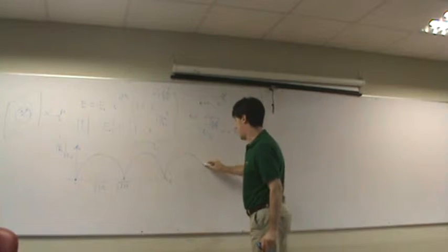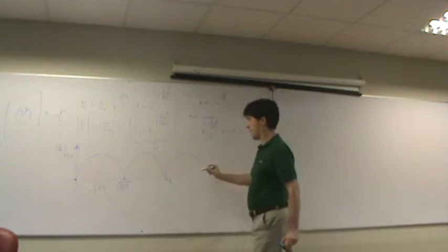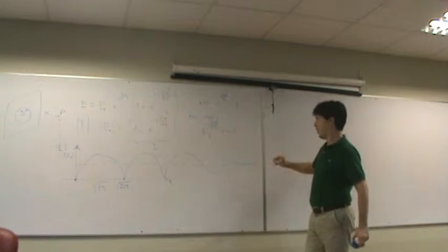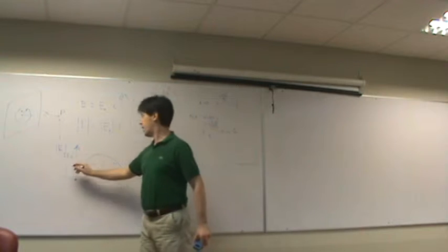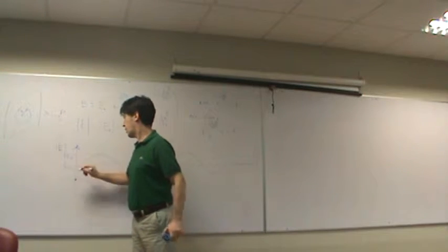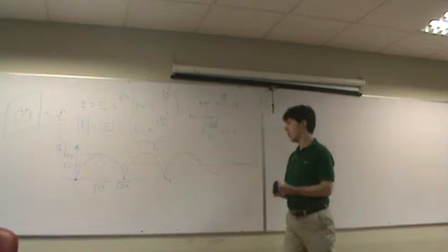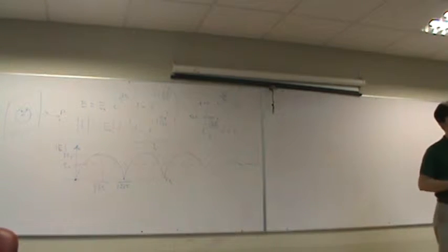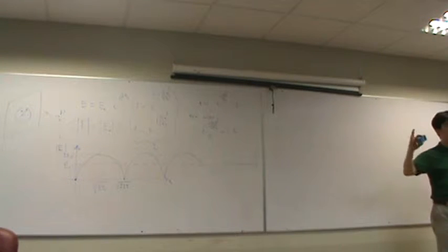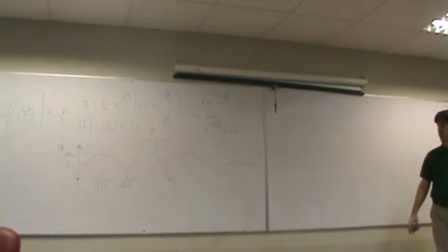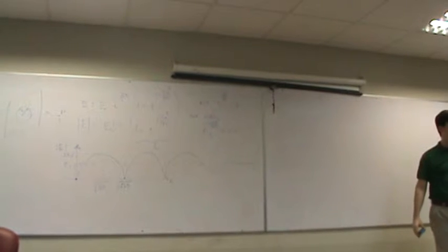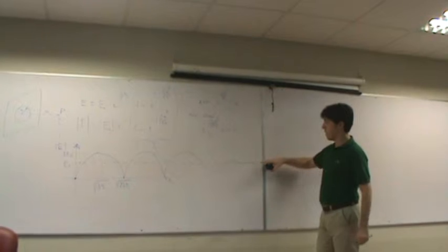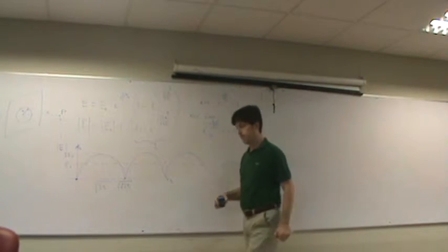And it will eventually converge to a value that is E0, the value in free space. This is intuitive, because when your aperture is very, very large, it's like really free space. So you must somewhere converge to the free space value.